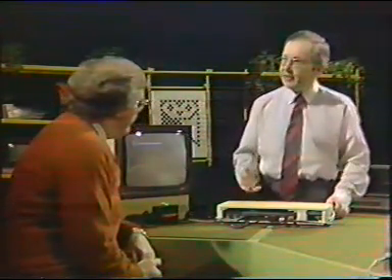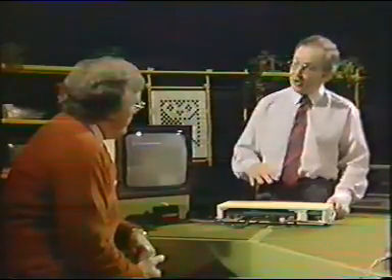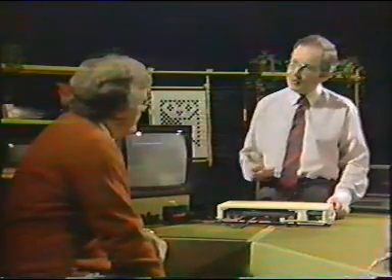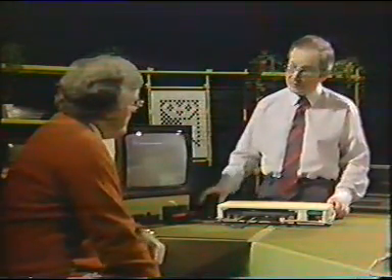That's right. So what? Well, you've got 8 control channels here. You've got 8 signals which can be switched on or off, and you could use those to control 8 devices. So in effect, you could make that turn the robot left, and this one turn it right, that switch the motors on, that switch it off, and so on and so forth. Any 8 things that you wanted to control on the output, and you could sense different things on the input, just by simple ons and offs.